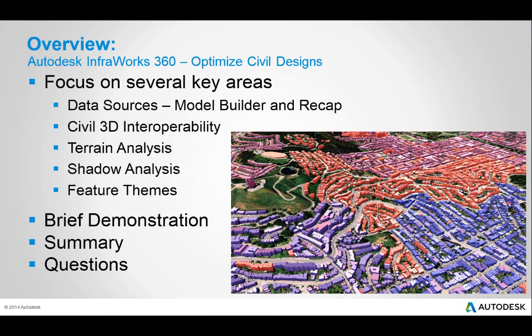We're going to focus on several key areas today, one of them being data sources, using InfraWorks Model Builder, and looking at Recap data sources. We'll also look at Civil 3D interoperability, terrain analysis, shadow analysis, and feature themes as they relate to picking a site to develop. We'll have a brief demonstration, a summary of what we've done, and a period for questions.